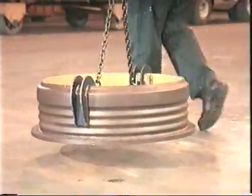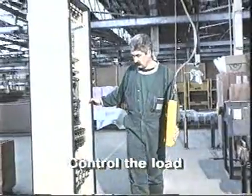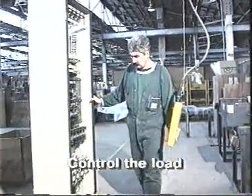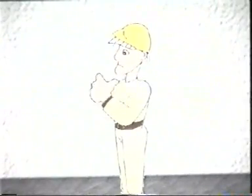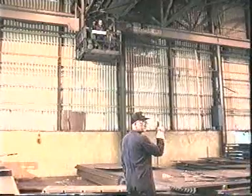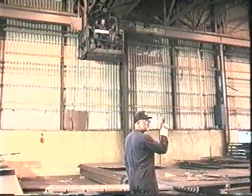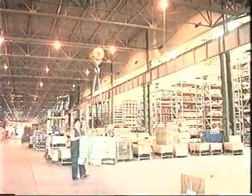When a crane is under pendant control, you should maintain a sufficiently close relationship with the load to ensure good visibility and safe handling. If this is not possible, then proceed only under the direction of a dogger. Where a crane chaser or dogger is employed, it is their responsibility to direct the crane operator and ensure that the load clears all obstructions.